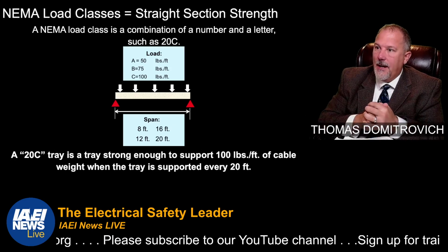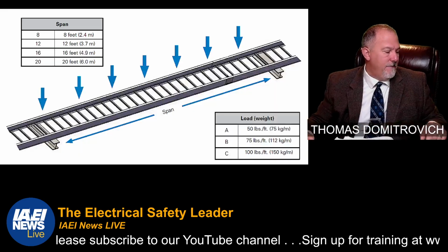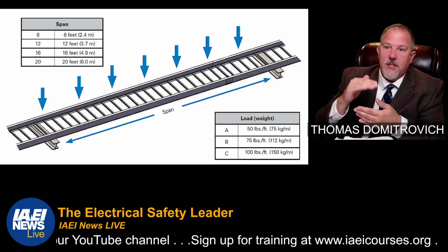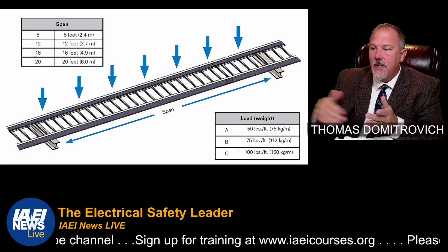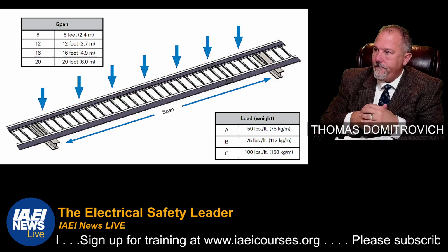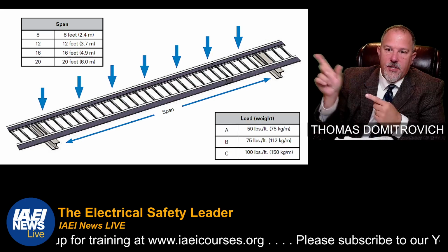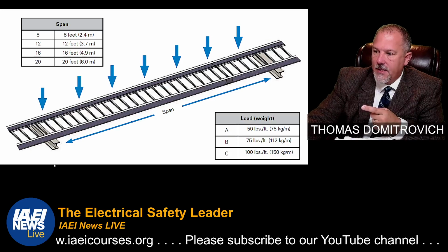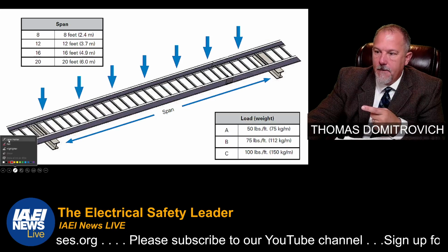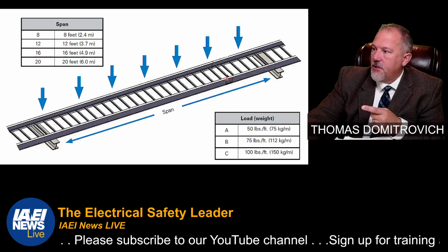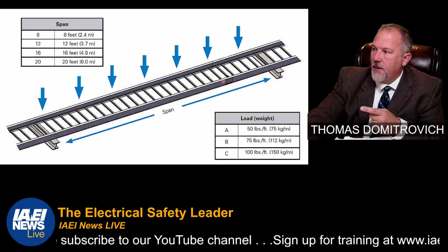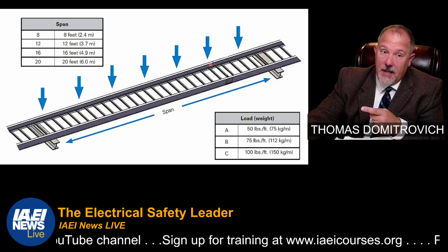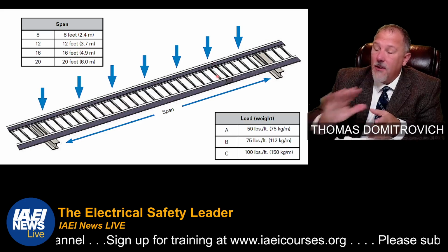And then that's your span, right? So that's your span over there. That's your 20-foot spans. That's every 20 feet of support. And you'll notice where the splice plate is on this one here. It's right here in the center. So I'm going to use my laser. There's your splice plate on this one that's between these spans. You never want to have more than one splice plate in between spans. So there are a lot of little details.